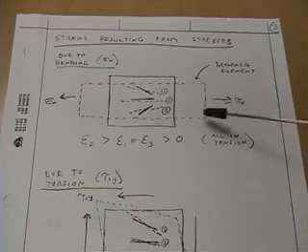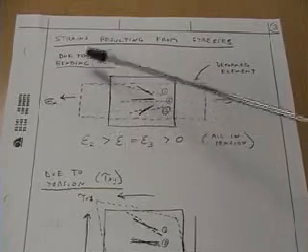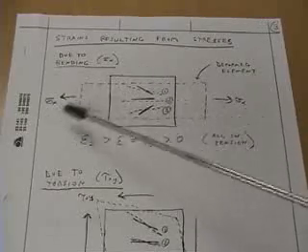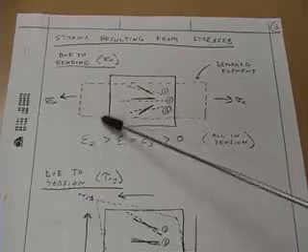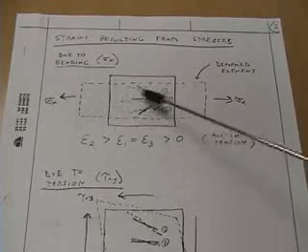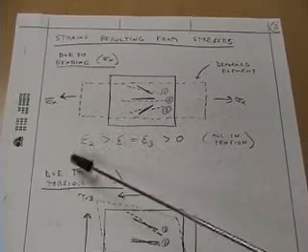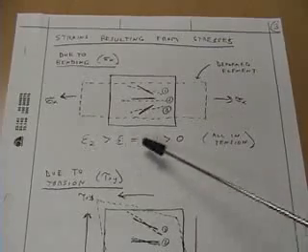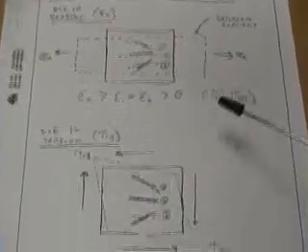These figures show a qualitative analysis of the strain being experienced by the rosette. First, we're showing the effects due to bending. So when an original element of material is stretched in the axial direction, this dashed rectangle illustrates in an exaggerated way how the material deforms. And in this case, the central gauge will be in tension and will be stretched the most. And the other 2 gauges, they will also be stretched slightly. But in summary, the strain experienced by the center gauge is going to be larger than the other 2. The other 2 will be equal because this is symmetric. All will be positive because they're all in tension.